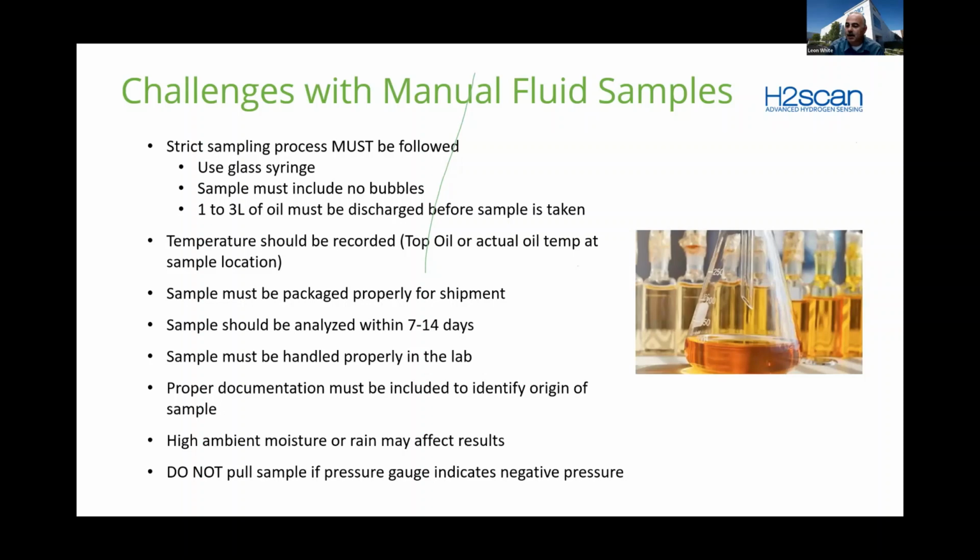So also a very important thing that I think a lot of people don't realize is if your transformer has a nitrogen system or is a sealed transformer and has a pressure gauge, you should always check the pressure gauge to make sure that the transformer is not in vacuum or negative pressure, because you don't want to open a valve and pull a bubble into the transformer that could potentially fail the transformer, or again, pull atmospheric gas into